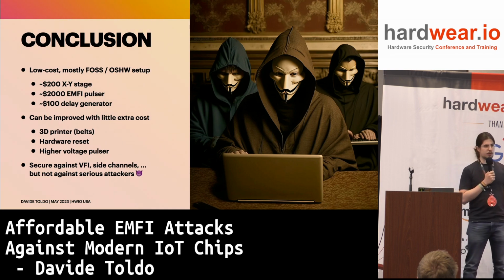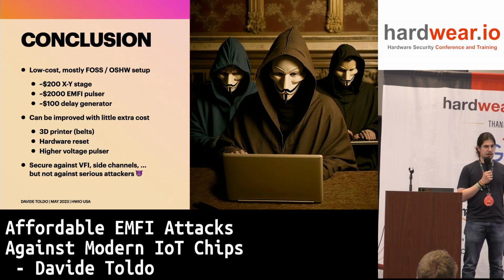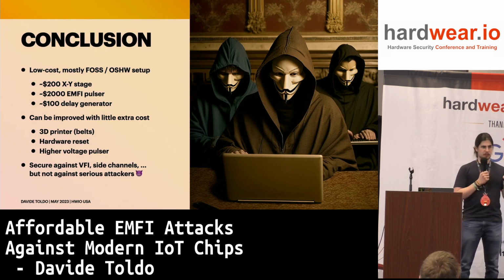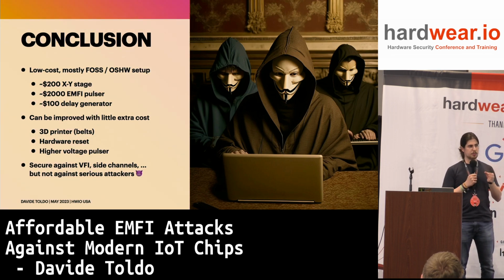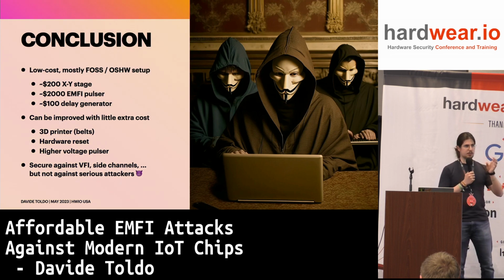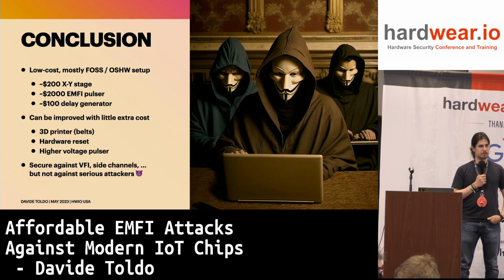So for applying this knowledge to a secure boot, for instance, you would have to also find the timing, but the area should be mostly the same, I guess. This chip does have crypto accelerators and crypto features, and I guess those might be in different areas of the SoC. Although in the end, your application code has to check the result, like what comes back, and that might be in the same area again. So, yeah. Okay. Do we have any other questions?